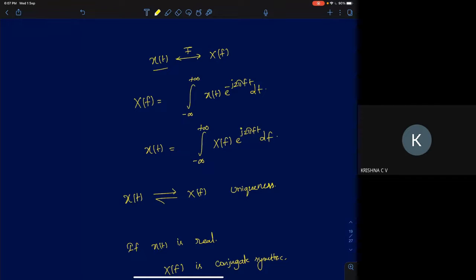Not only that, if you have a time domain signal and you transform it into a different form, which we will see is the Fourier transform, then by the knowledge of that Fourier transform we can greatly simplify or have a better understanding of the signal, and it will also greatly help us in designing these signal processing and radio frequency systems. Now, this transformation from time to frequency is given by this very simple Fourier integral, where X of f is given by the integral of x of t e power minus j 2 pi f t dt.